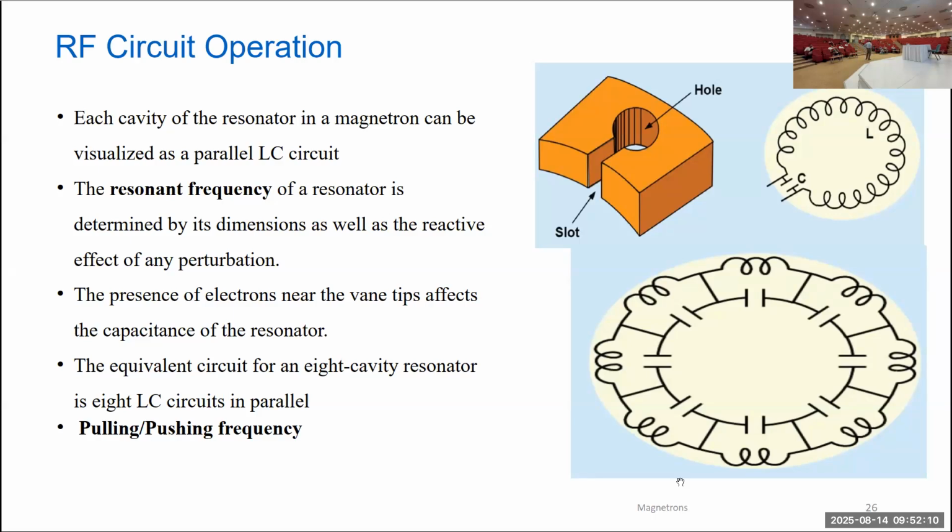Does the space charge affect the resonance frequency in this? Yes, space charge affects the resonance frequency because it affects the capacitance of this cavity. And the frequency is 1 over the square root of LC. If capacitance decreases, frequency will increase. If capacitance is increased, frequency will decrease.